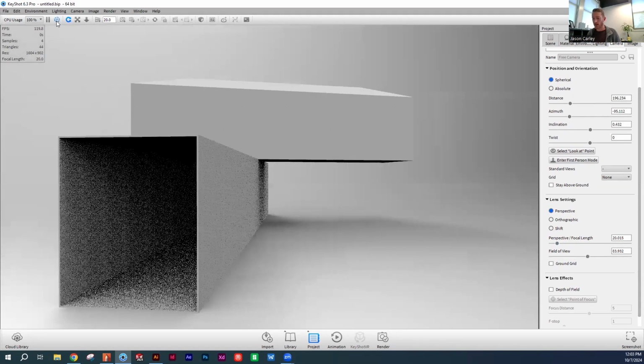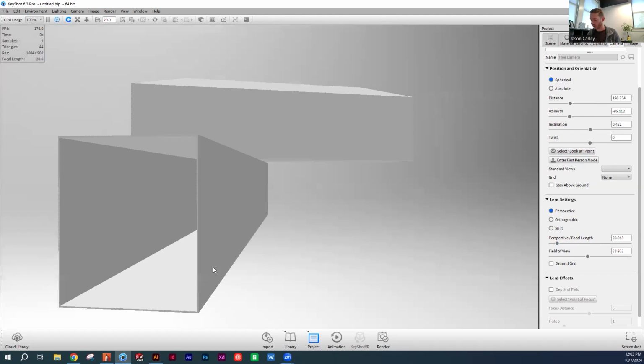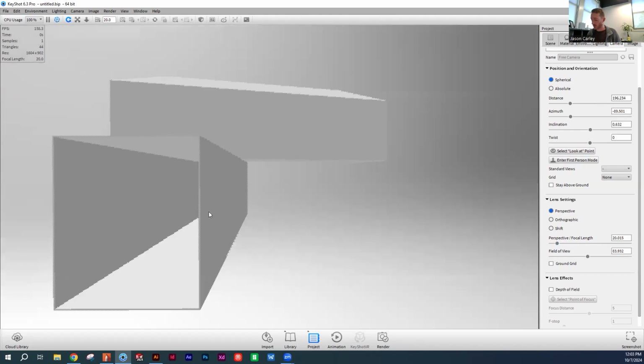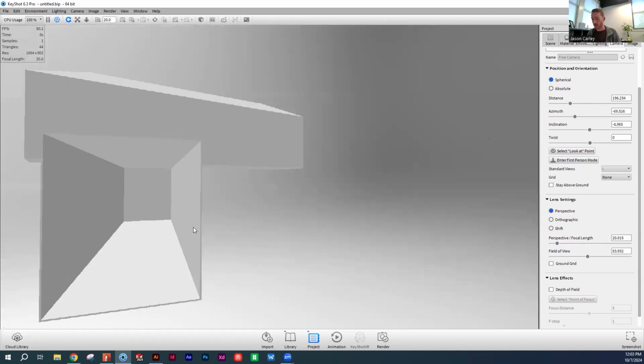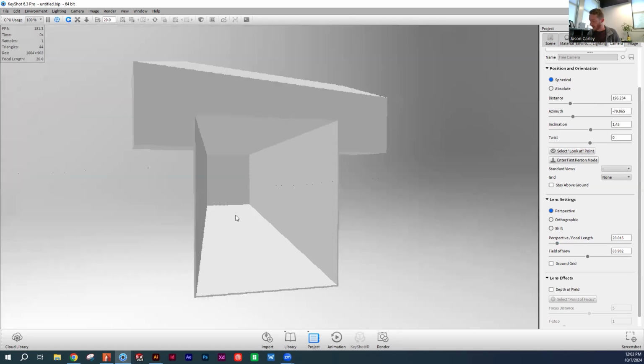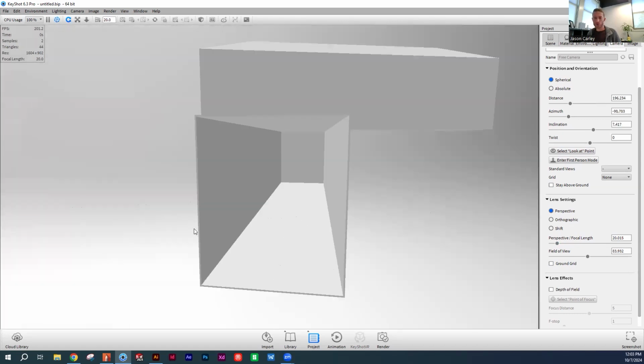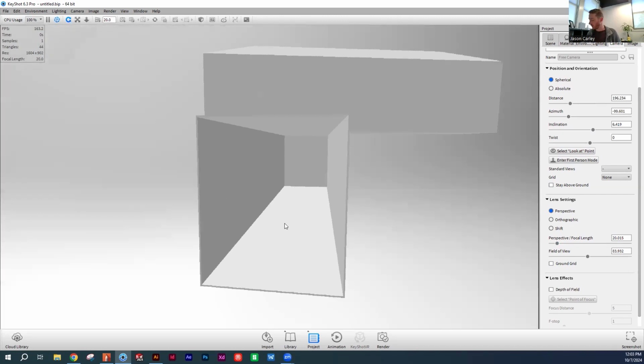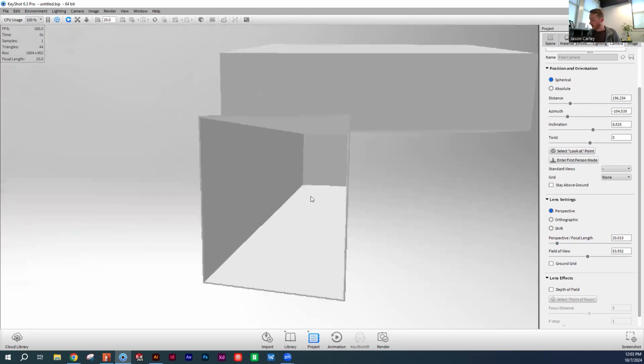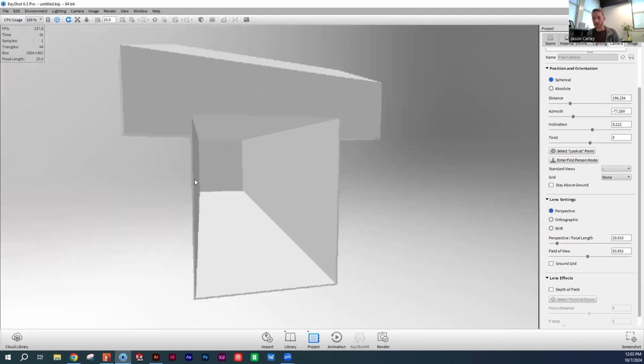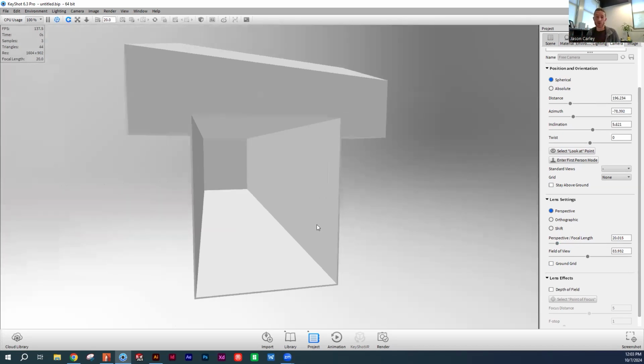All right, I'm going to toggle on performance mode really quick because I want to show you the interior of this. So this takes out all of the shadows that I had in my environment. For some of you who want to do an interior microenvironment, this becomes really handy, right? You get the perspective lines of the walls in there if you just shell your model in SolidWorks.